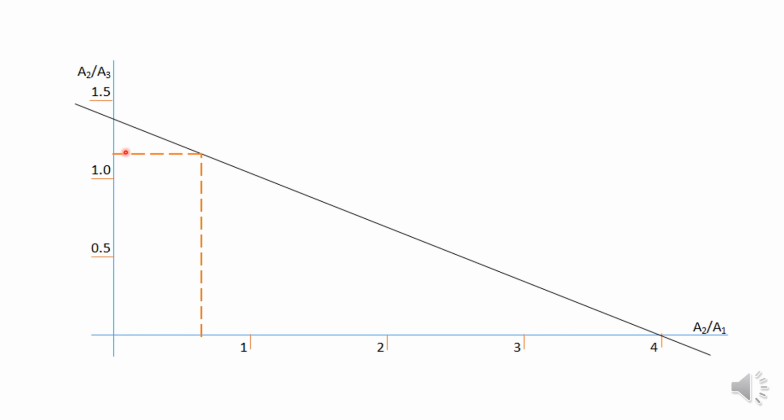And you've already chosen the F, so you know what the forces in the members will be, and you can go ahead with a design like that. So I'm just showing you here how the compatibility equations can be used in design also, not just in the analysis of the truss.